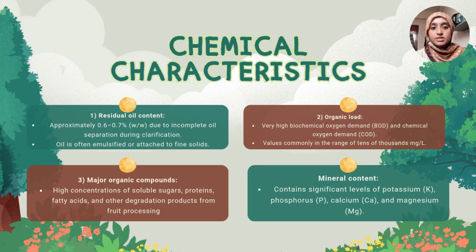For the chemical characteristics, first is residual oil content, approximately 0.6 to 0.7%, due to incomplete oil separation during clarification. Oil is often emulsified or attached to fine solids. And the second one is organic load, which is very high BOD and COD, with values commonly in the range of tens of thousands of milligrams per liter.